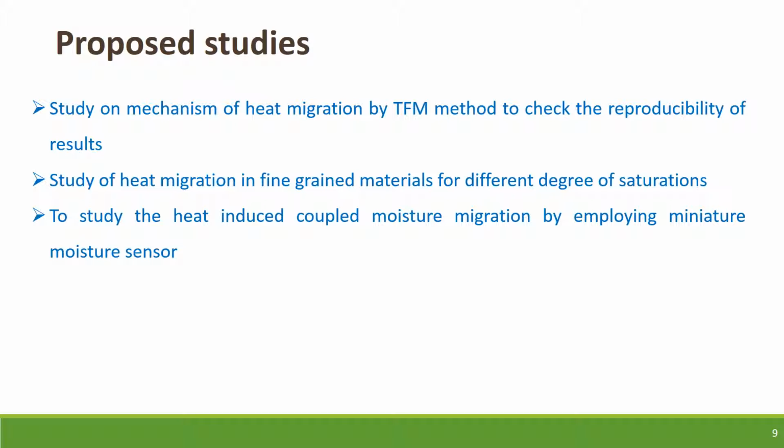Next would be the study of heat-induced moisture migration, which is a coupled phenomenon and has to be studied. One of the possible ways would be by employing miniature moisture sensors in the mold which has been developed and described in this study.